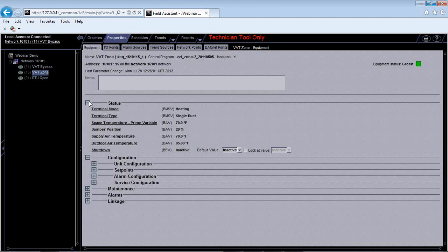And when something like that happens, your zone would go to its minimum position, close off so that you're not bringing in cold air and making your space colder. And that's described again in the installation manual. You can look at it too. But it gets a little confusing when you have a zone that you think needs heating, or when you think it needs cooling, but it's actually in heating mode because the air source hasn't actually switched into the cooling mode yet.